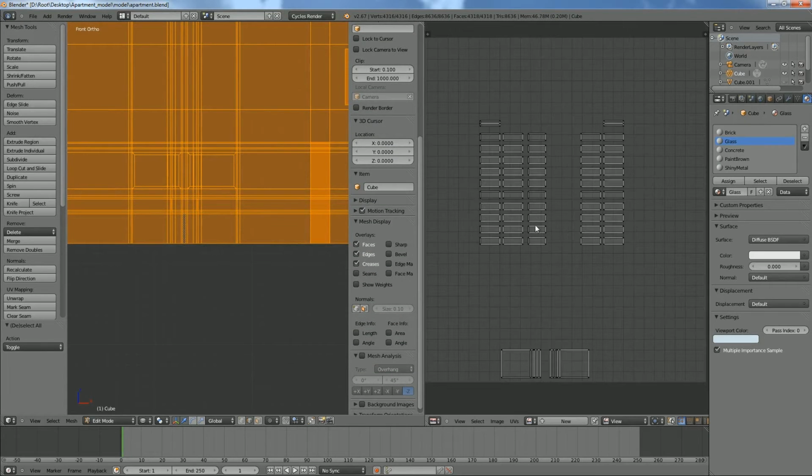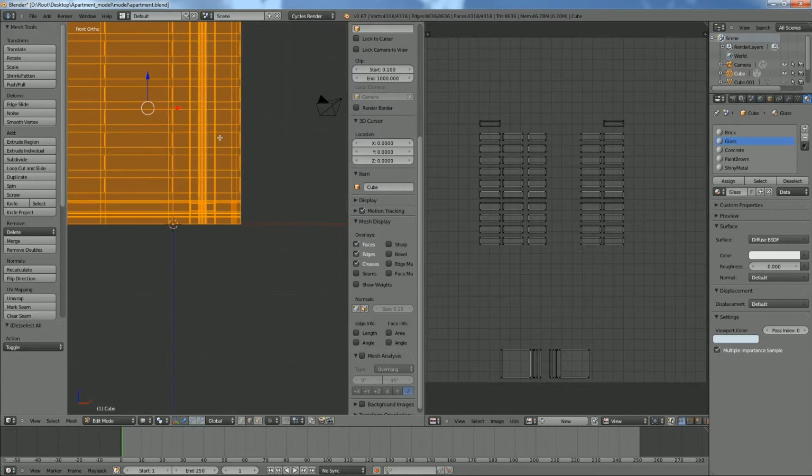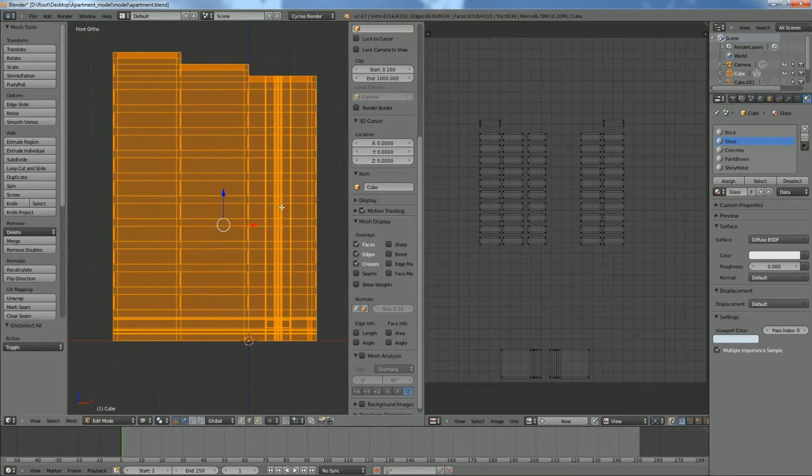And actually, we're going to also do something a little bit different. We covered this in the desk texturing tutorial, so you can find more on that. But we need to do separate UV maps for each of the different materials, just in case we have images whose aspect ratios conflict. It'll change how some of the aspect ratios of your mesh appear on the images themselves, and so it could potentially mess up the stretching, and stretch your tile or your textures you're using.